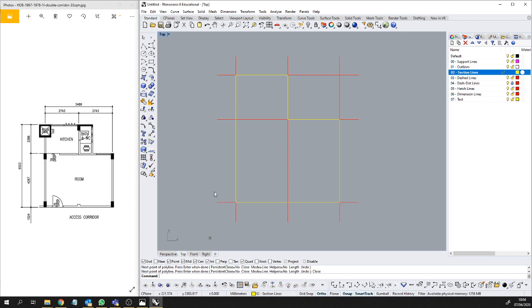Generally, the outer walls of buildings are thicker than the inner walls. In this drawing, we cannot see this, so I think all the walls in this case are about 100 thickness. Normally, what you can do is use for outer walls about 250 to 300 and inner walls around 100. But for simplicity, we'll use 100 here as well.